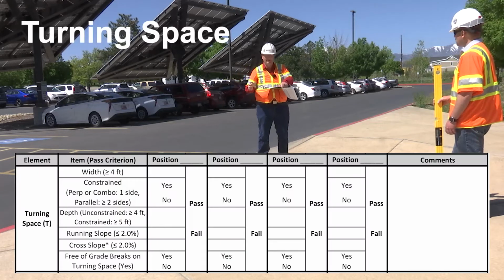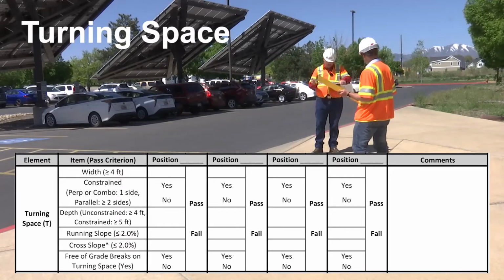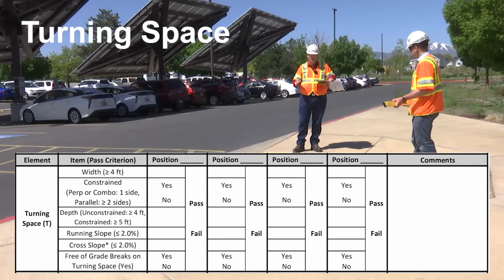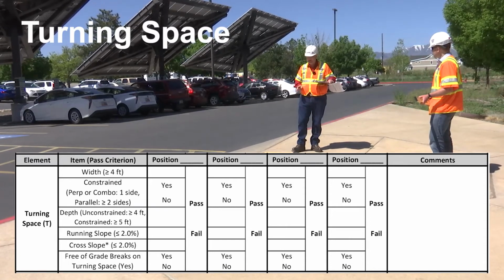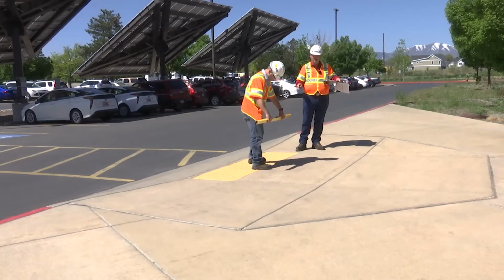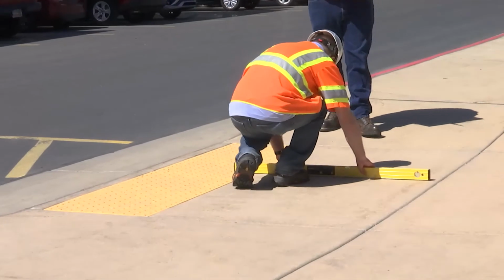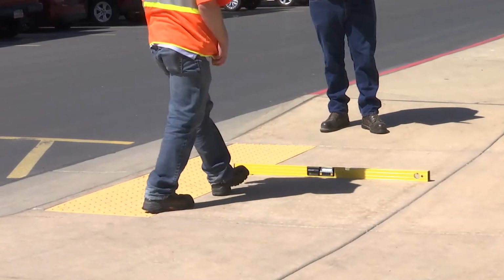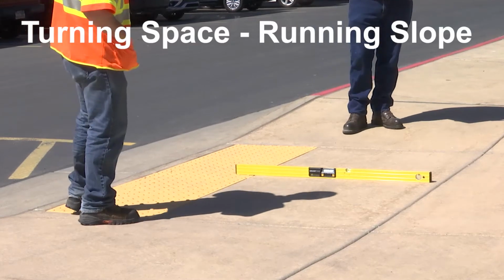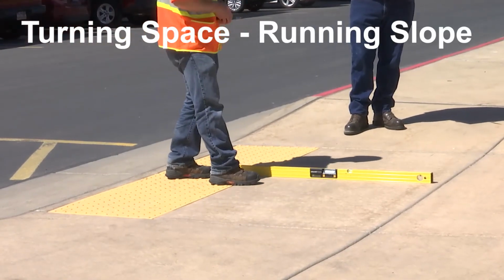Next is the turning space. We'll take the measurements of the turning space, the running slope, cross slope, the width, the depth, and we'll determine if it's constrained or unconstrained. So first off, we can see that there's no barriers around it, so it is unconstrained. The running slope of the turning space is 1.7%.